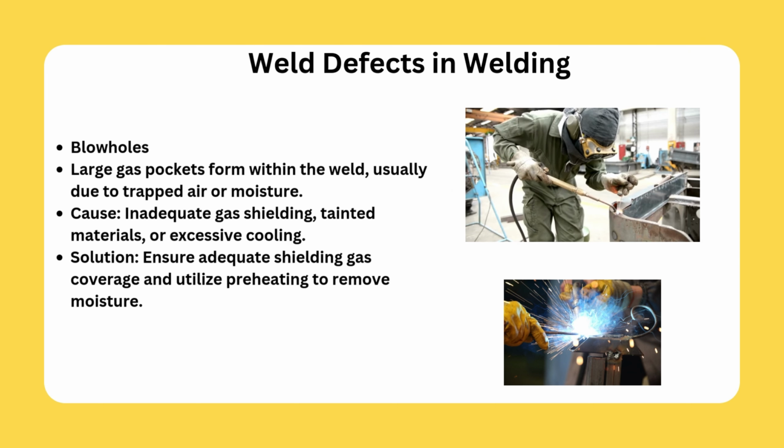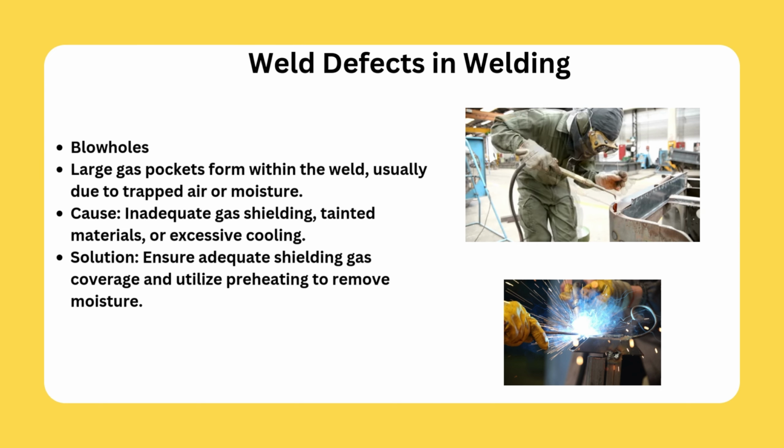Blowholes. Large gas pockets form within the weld, usually due to trapped air or moisture. Cause: inadequate gas shielding, tainted materials, or excessive cooling. Solution: ensure adequate shielding gas coverage and utilize preheating to remove moisture.